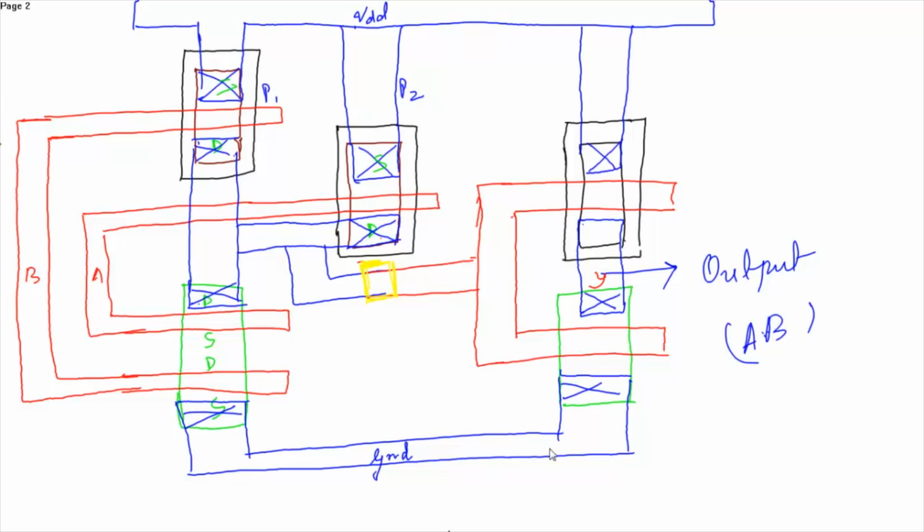Now this is the whole layout of the normal form of the AND gate. So we can label it. This is the metal layer. You can see this exactly represents, like I can show you here. We had the PMOS in parallel, which was connected to VDD. This PMOS is this one P1, this PMOS is this P2.